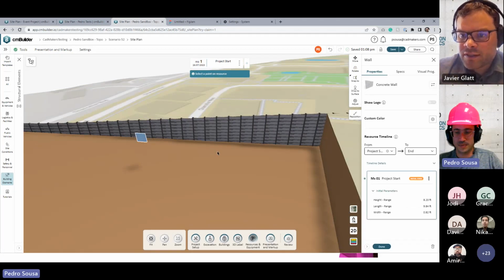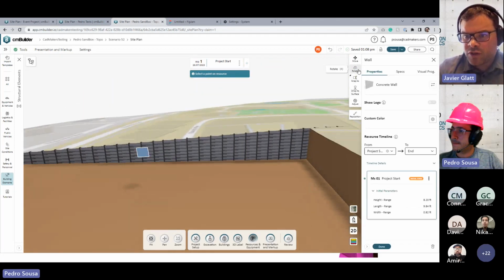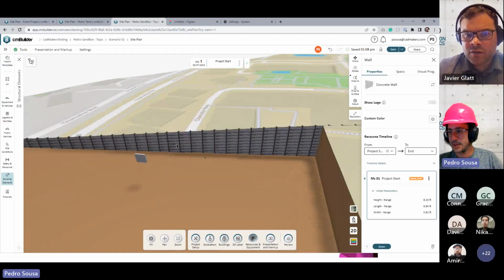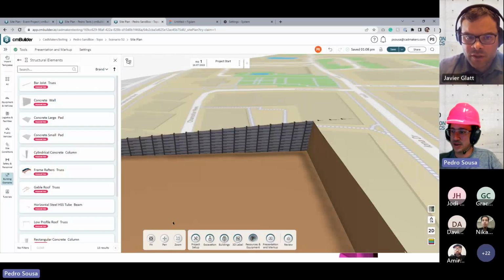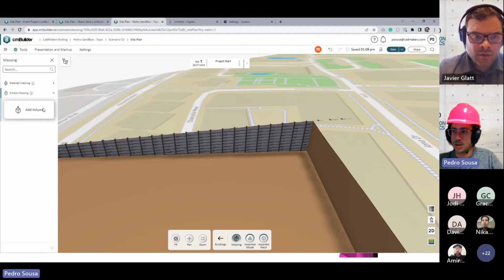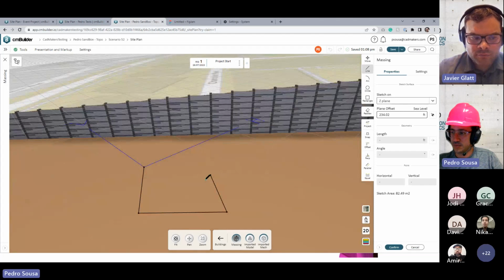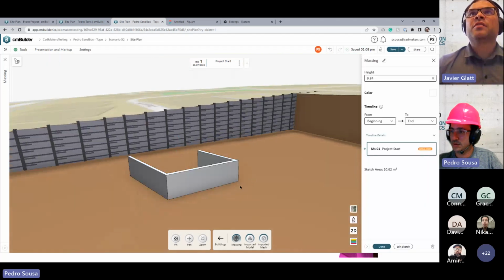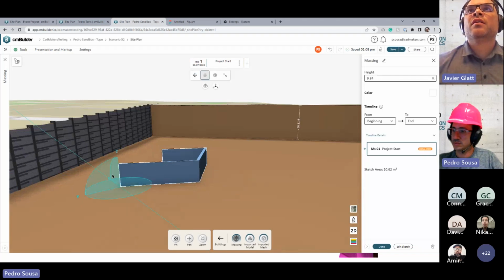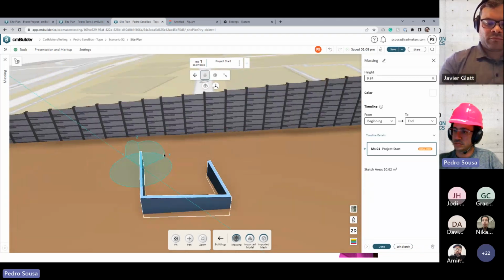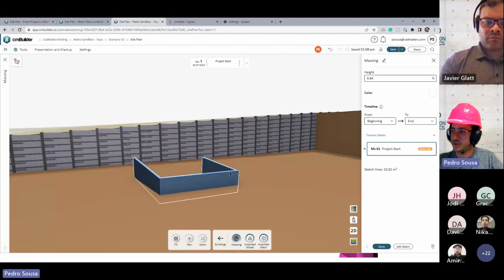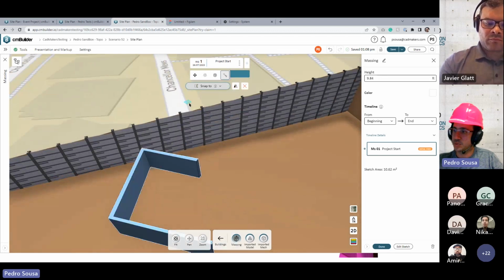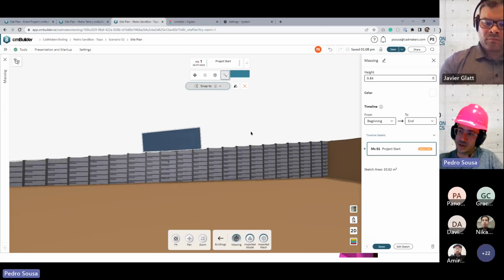You muted. Is that what you meant, or slope? I'm guessing you meant slope walls from a massing, not from the excavation. Oh yeah, so with slope walls for massing, you can only do that by rotating it. Yeah. So I think this is something we're revamping in the massing feature. It's a huge overhaul. So we can check if that's actually included. Let me ping the team right now, see if we're going to have that. You can also use the snapping for the massing as well. So if I want to snap align this face with this part, I can have it matching now.